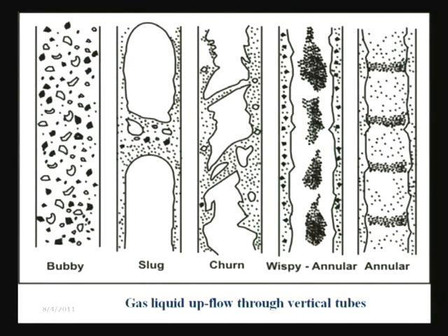So, therefore, the annular flow can be characterized by a smooth interface or an undulating interface, depending upon the relative velocity of the two phases. The main characterization is that there is a continuous liquid film on the wall and a continuous gas core between the two liquid films. There may or may not be droplets of liquid or wisps of liquid in the gas core. Some researchers have tried to differentiate between the wispy annular and the annular flow, but we are not going to do this for our particular purpose.